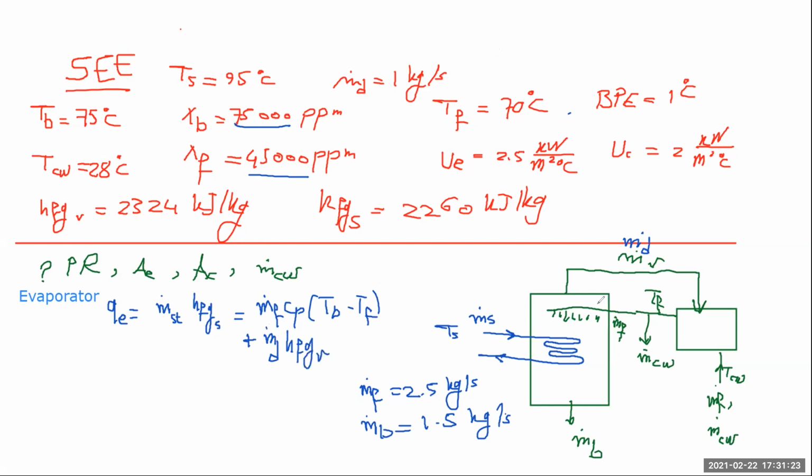So all the feed has entered here. All of it will flow on the horizontal surface of the tube bundle, and all of it is going to be heated to the saturation temperature. In addition, part of it is going to evaporate. We have a mist eliminator here to make sure that whatever is leaving is pure vapor, and any droplets of the brine are going to fall down again at the bottom so that they are rejected.